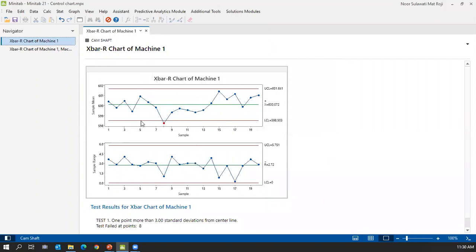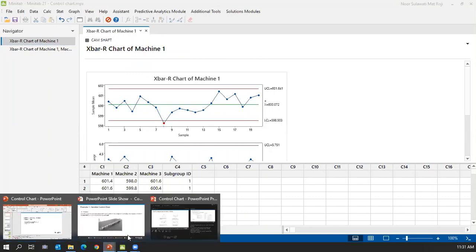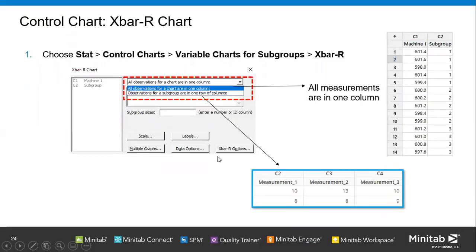But for the mean average one, there are samples outside of this control limit. All these values here are calculated from your data set. No need to include 3 sigma or 2 sigma or 1 sigma. So this one is the X bar chart. This one is your upper control limit, and this one is the lower control limit. So I will show how Minitab calculates those values.